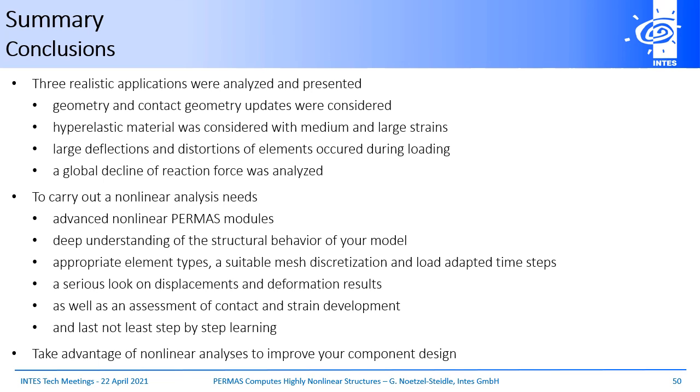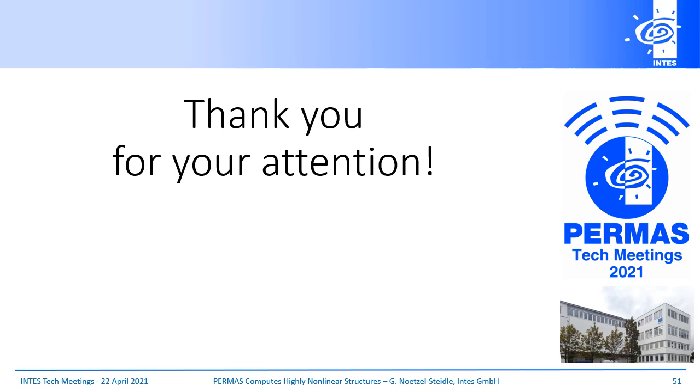To carry out a nonlinear analysis needs advanced nonlinear PERMAS modules, deep understanding of the structural behavior of your model, appropriate element types, a suitable mesh discretization, and load-adapted time steps, a serious look at displacements and deformation results, as well as an assessment of contact and strain development, and last not least, step-by-step learning. Take advantage of nonlinear analyses to improve your component design. Thank you for your attention.